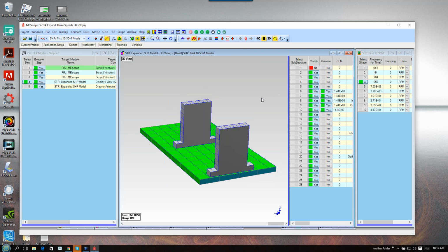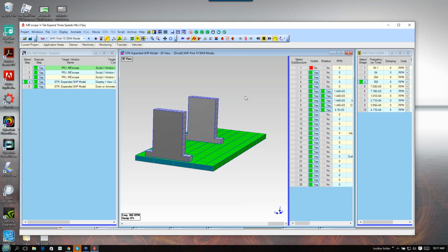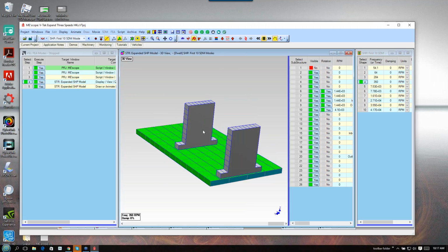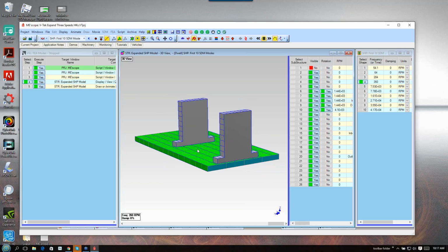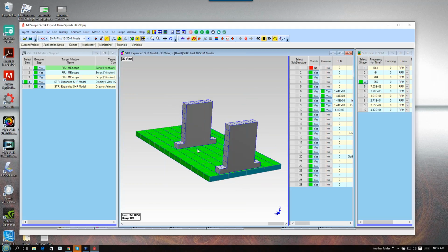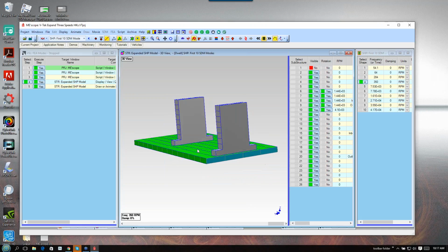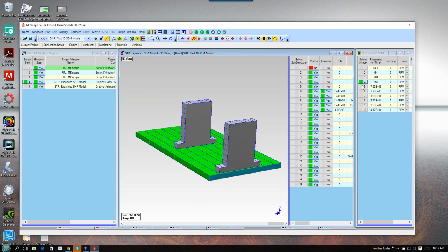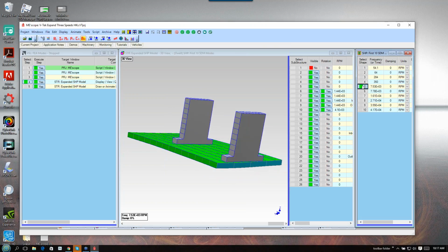The rigid body modes were created with our SDM software by modeling the attachment of each of these bearing blocks with stiff springs to the base plate. So I simply solve for the FEA modes of the base plate, then the bearing blocks, and then I used SDM to attach them together.